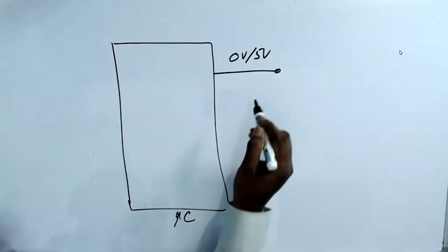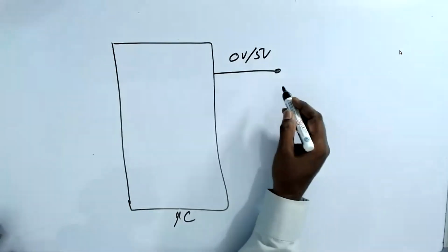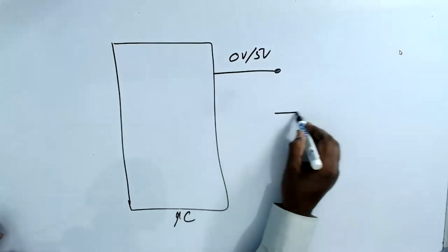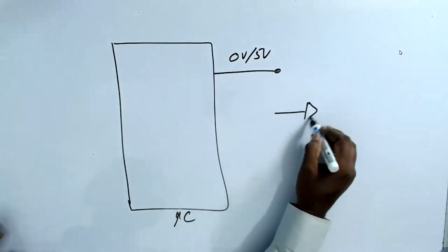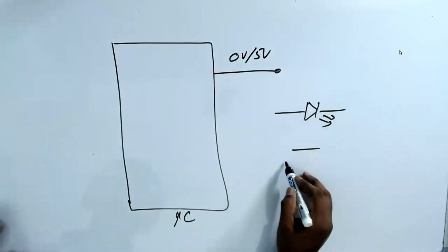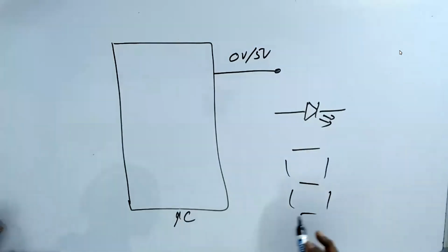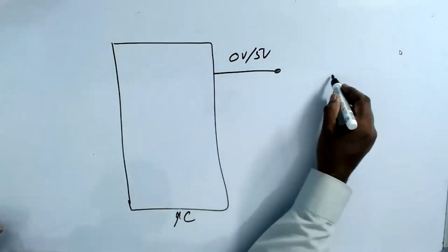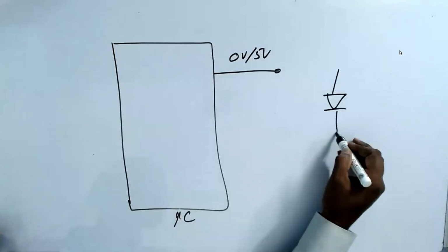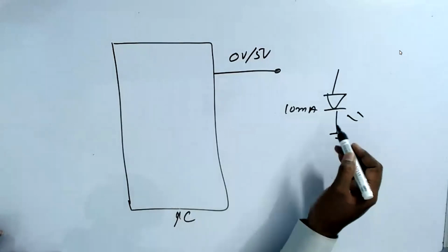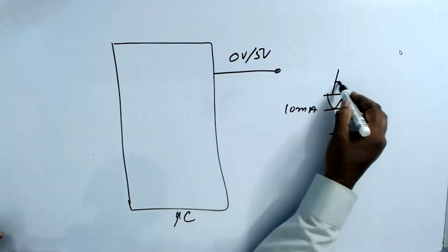Now we have discussed two devices. Actually, we discussed the LED and the LED arranged as a 7 segment. We have seen that the LED draws about 10 milliampere and takes 2 volts.